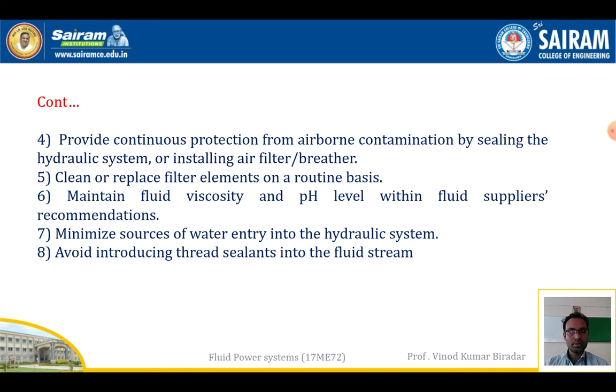The fluid viscosity we have to maintain properly, and minimize the source of water entry into the hydraulic power system. Okay, the entry of water should not be more than required. So if you are using more water, then again the system is corrupted. And the eighth one is to avoid infusing thread sealant into the fluid stream.